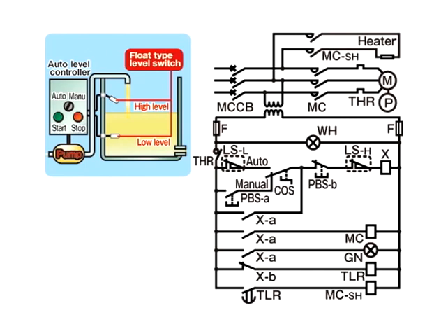Make sure that the MCCB is turned off when searching for the cause of the excess current. When the problem has been resolved, turn the MCCB and THR on and start operation by switching the changeover switch to manual mode.